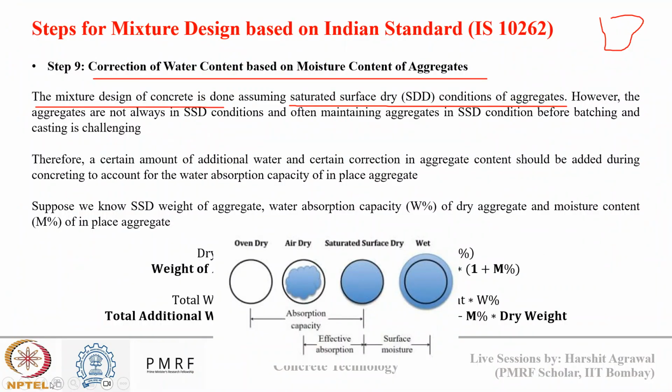Okay, so in this figure, this third image represents an SSD aggregate. The aggregate is completely saturated from inside, so it won't absorb any moisture from the water that I am adding for concreting. This is the aggregate that we have assumed till now; till step 8 we have assumed aggregates are in SSD state.